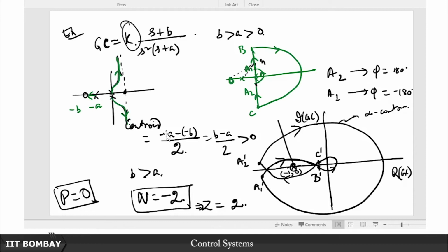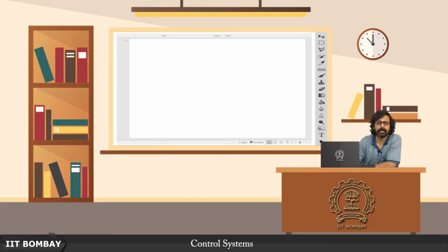So you see that this Nyquist criterion actually allows us to draw all of these conclusions that we drew using the root locus earlier. So I will conclude this discussion on examples with a final example. The earlier two examples we have chosen are not that interesting, in the sense that you have this pole pair at the origin, so you have to take the dent around it, but there is nothing much you can do.